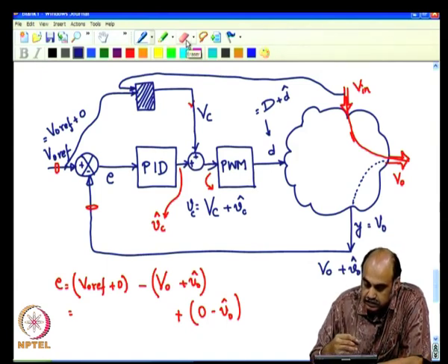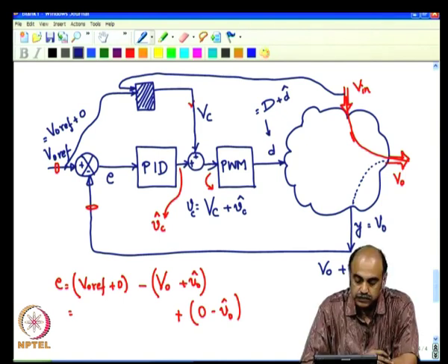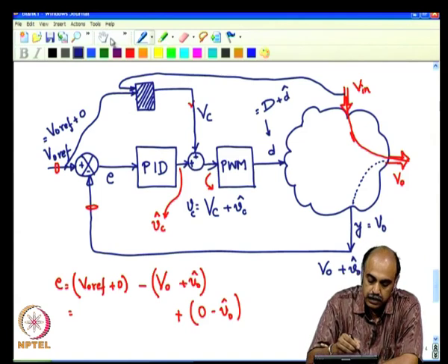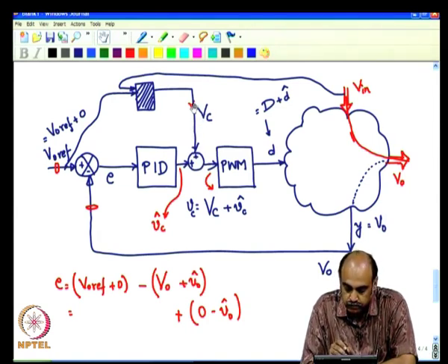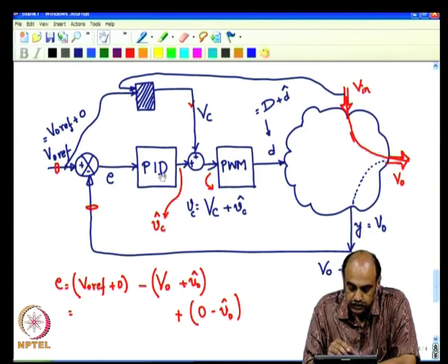But remember that we can separate into the steady state portion. So, the steady state portion can be addressed and taken care of by the feed forward terms. The feed forward terms can be added either at this place or after the PWM, appropriately. You will get to understand the context and the nature, and by which way we will be adding, once we know all the circuits put together. If we allow the PID or the controller portion to take care of only the small signal terms, then they will respond much faster, the dynamics will be much faster. However, you could allow the PID to take care of the entire signal, both steady state plus small signal too. So, both are okay, but the only thing is that the dynamics will be slower.